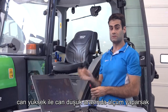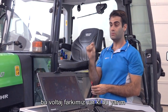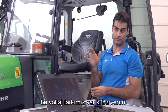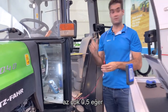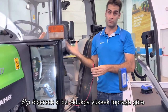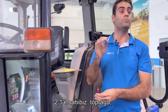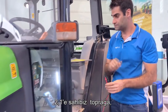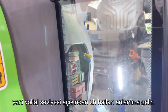If we measure from CAN high to CAN low, we have this voltage difference, which is half a volt, more or less 0.5. If we measure 6, which is CAN high to ground, we've got 2.57, and 14, which is CAN low, 2.1, comparing to ground. So that means CAN lines, in terms of voltage level, it's okay.